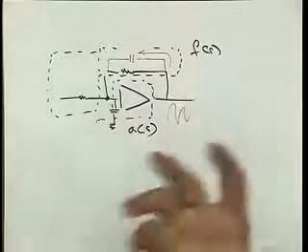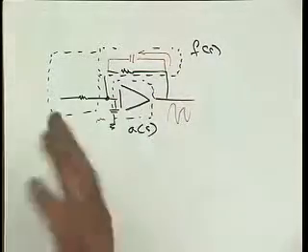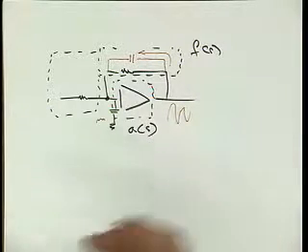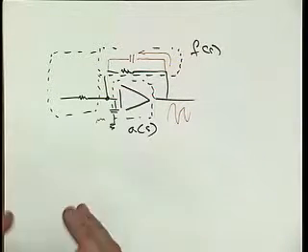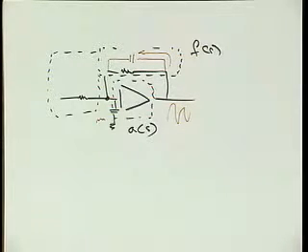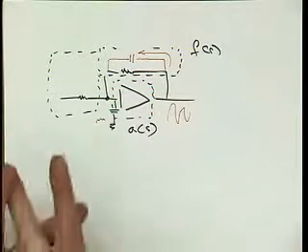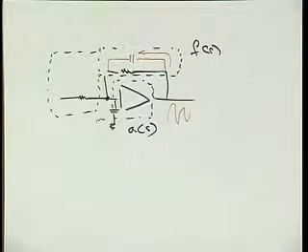In fact, you can run AC analysis of circuits in SPICE, circuits that are totally unstable, but the AC analysis just kind of looks fine, right? Sometimes it doesn't converge during trying to find the operating point. But if you really want to verify stability, then we have to look at T of S. The other approach with SPICE that also kind of works, and is a little bit more general in some sense and more restricted in others, is transient analysis, because there we really can exercise the circuit in pretty much the same ways the real circuit would be exercised on the chip.